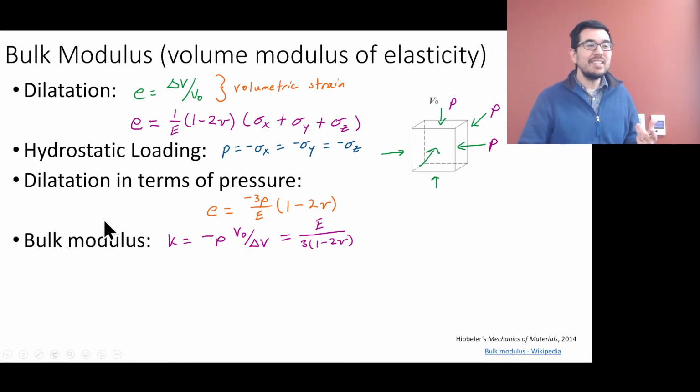So this is kind of like a volumetric springiness, essentially. We have spring rates, we have spring constants, but it's not really a spring rate or spring constant. It's actually more like an elastic modulus. We think of it as a spring rate maybe for right now, but look at the units again. We deal with a lot of pressure in this class. This is dimensionless in the denominator, and once again, the elastic modulus is in units of pressure.